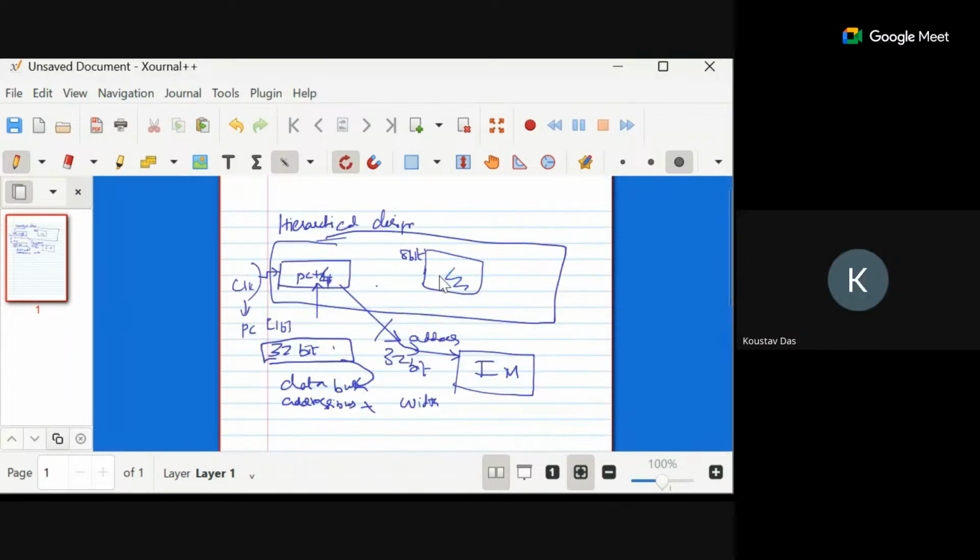The address bus is... Okay, let us hold. Forget about this part. I told you the program initially I designed on a previous system, which is 4 bytes, I mean incremented by 4 each time. It means 32-bit addition, and 32-bit addition refers to the instruction address pointer. I mean the next address, the address width of the program counter is 30-bit. Okay, what is the size of this instruction memory?